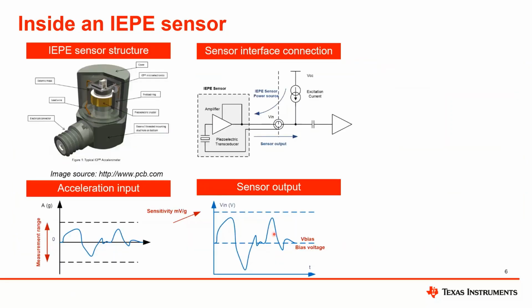I'm going to elaborate a bit on the IEPE sensor, as it's the industry standard of vibration sensing. The interface between the IEPE and the modules are standard. So all IEPE sensors can work with any IEPE interface module, regardless of manufacturer or brand. The IEPE sensor structure is shown here on the upper left.